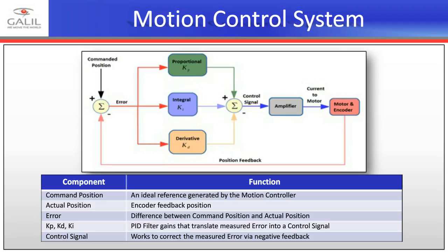Standard or current technology uses an analog signal, so the control signal and feedback are primarily what we'll be speaking about today. Standard control uses either an encoder feedback or analog feedback for position information, and then an analog control signal to the amplifier, typically plus or minus 10 volts, which is then translated into a current, a torque in the motor, etc. The benefits of this control scheme is that it's an established technology, decades of work behind it, very well understood in the industry.